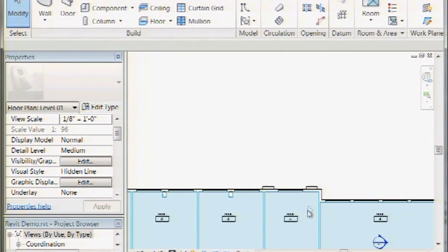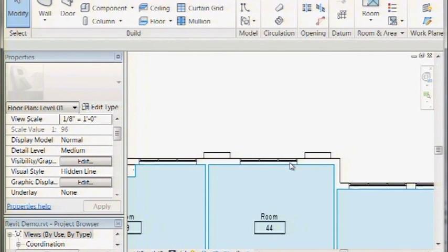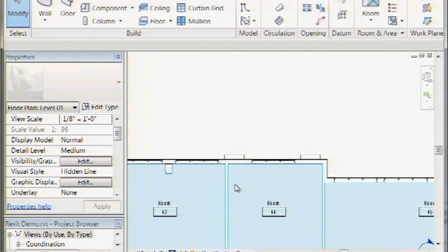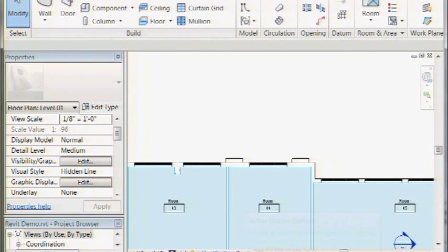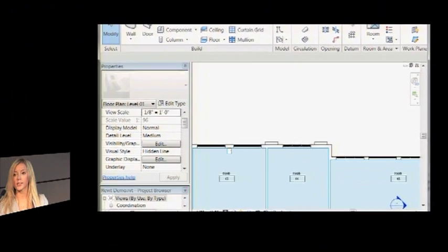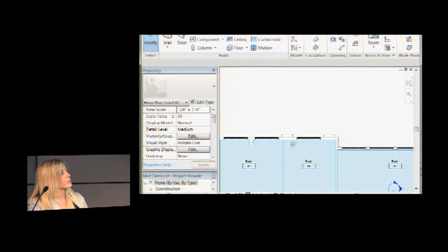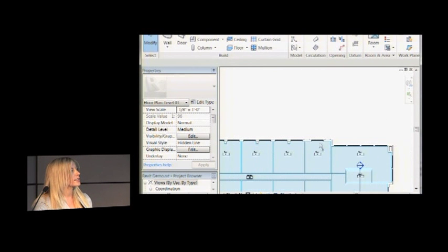Another problem we had a while ago, and I've been out of the design side for a while, so I don't know if it's been solved in Revit, but when people would layer floors on top of a large floor slab, and the reason for this was the inability to add different finishes to separate floors. So you might have a very thin floor in here that shows there's carpet in this space and this room has tile. So in doing that, you can actually hide hundreds of rooms underneath this, in between these two. There might be a millimeter gap, and you may not know why all these rooms are layered on top of each other. So any of the layering, it doesn't work.